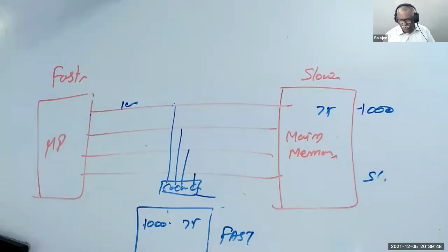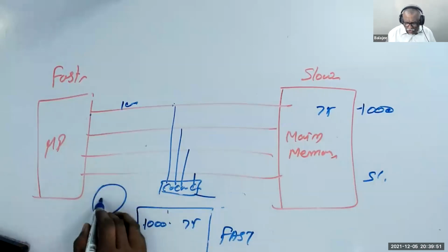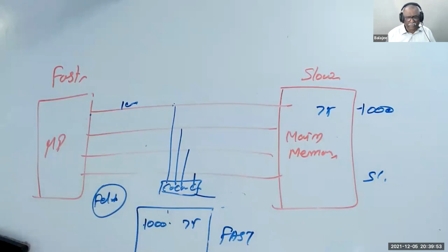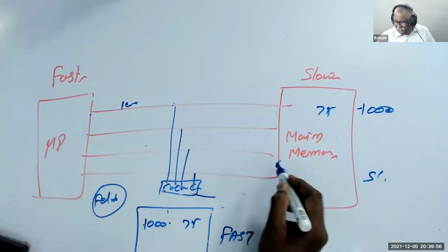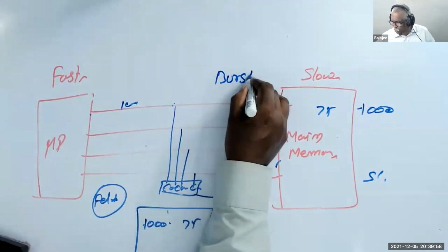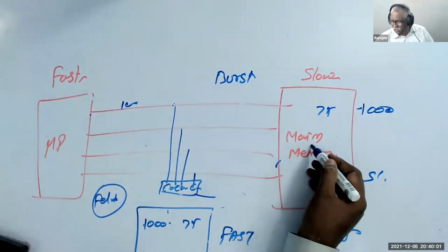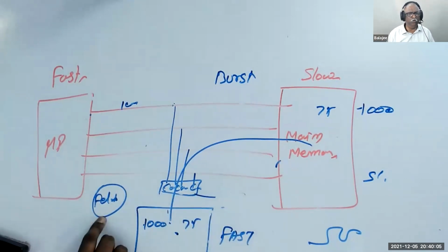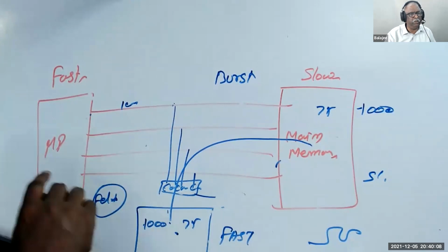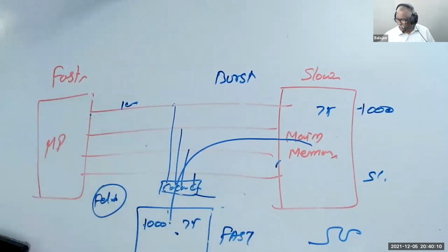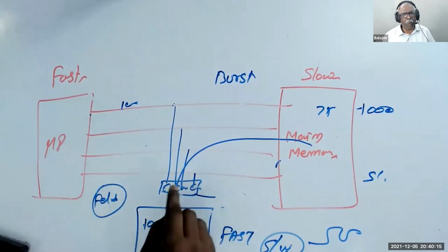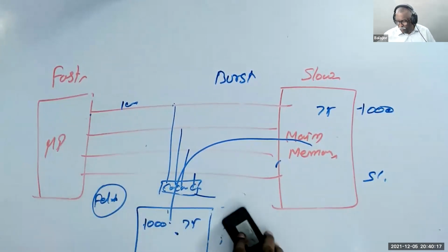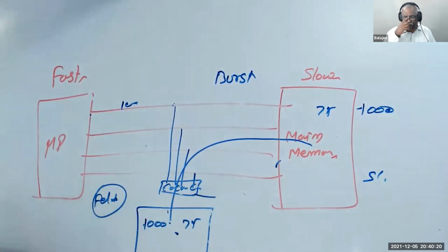Now, what we have here is a unit called the fetch unit. He will do the burst access. Every clock, one data from main memory gets transferred to the cache memory. That's what the fetch unit does. So next time onwards, the microprocessor will take from the cache and your software will be faster. I'm just explaining why they use the burst mode. It may confuse you, I don't mind. I'm trying to tell you what AHB is.